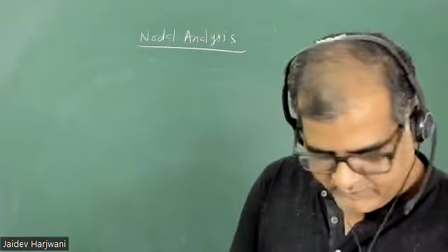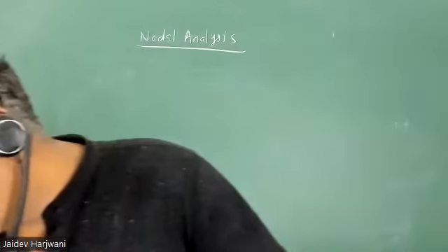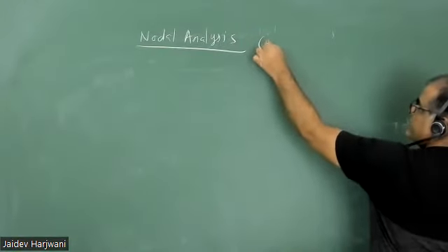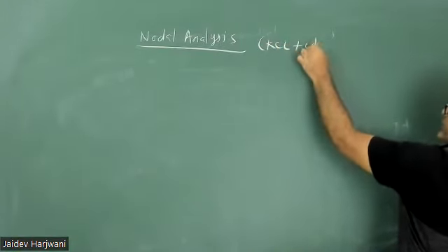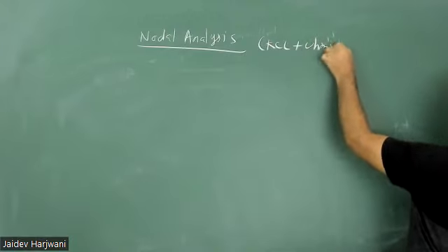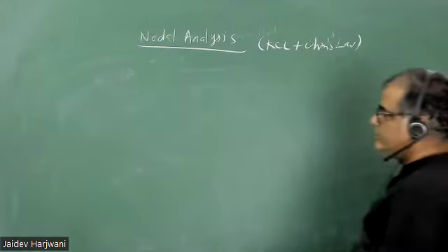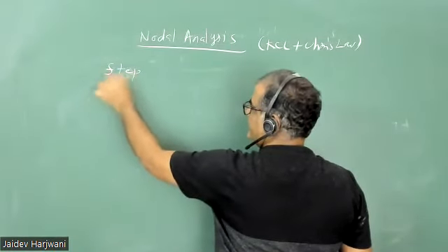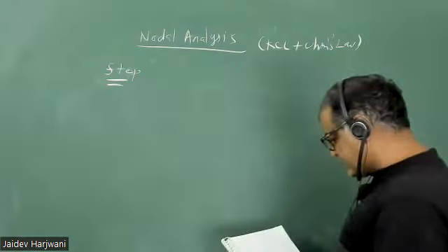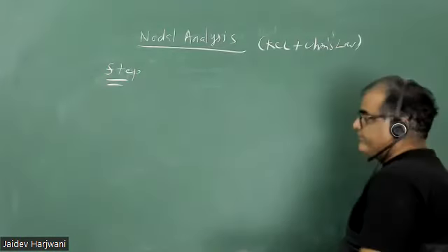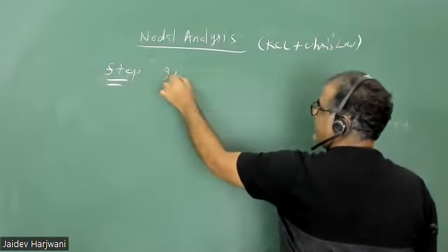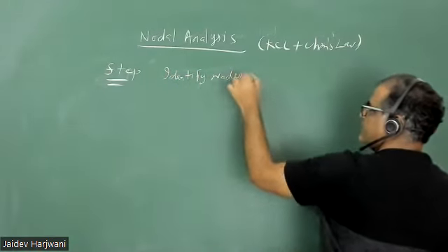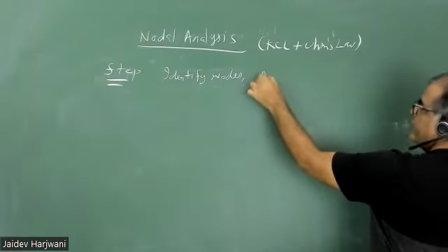Before I tell you what nodal analysis is, note that nodal analysis is basically the combination of KCL plus Ohm's law. You just note down the steps of this technique. Step number one: identify nodes, and assume there are n nodes.